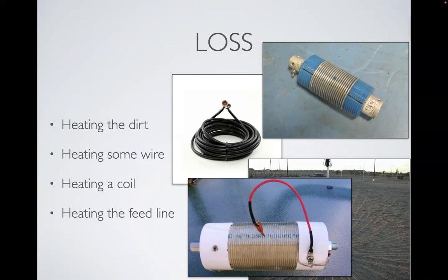Circulating currents, exactly. The current is going to circulate around that coil and that shorting wire, and it's going to warm it up. And that's not what you want. Ideally, you'd want to break that circuit and not have it be connected like that in a loop, or you can put a shield over it.